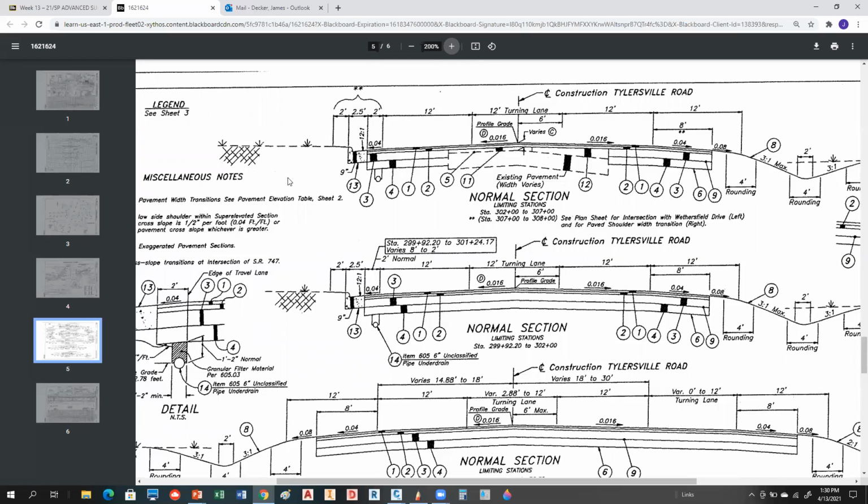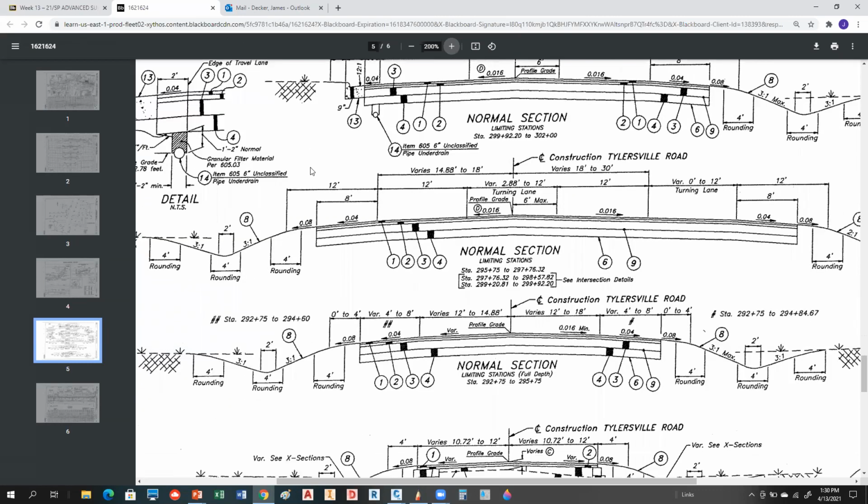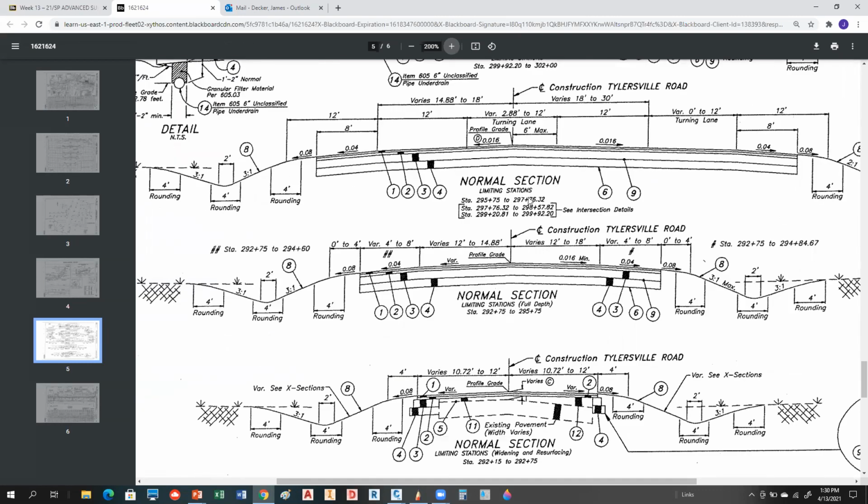Yes. Okay, so yeah, on a highway they do that by station. You can see this is really involved. You better be aware what typical section they're using for what station, otherwise you're going to lay it out wrong. Okay, so you've got to really watch that.